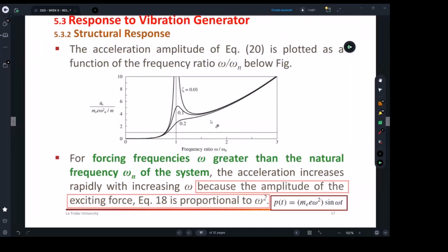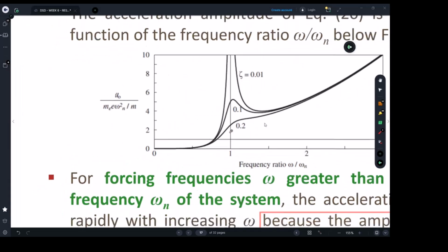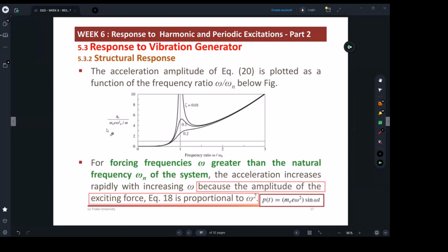That's why you're typically going to have this response. In the real test you're going to have specific values, maybe 2, maybe 1, depending on how much mass we're using in your experiment. But in reality, when we do a test, we study the structure, see its limited capacity, and go with good safety factors. You don't want to break the building that you're testing.